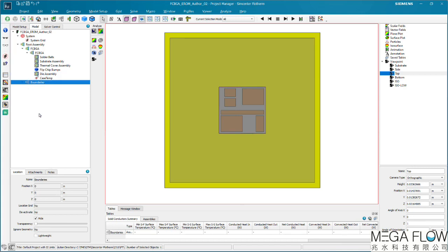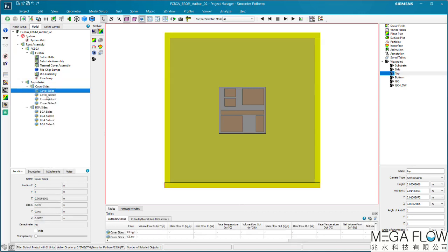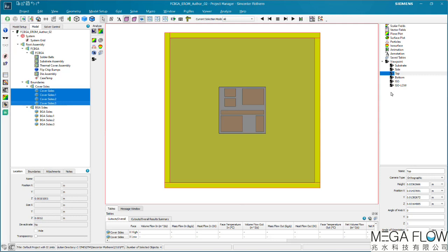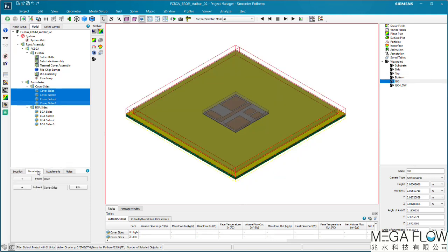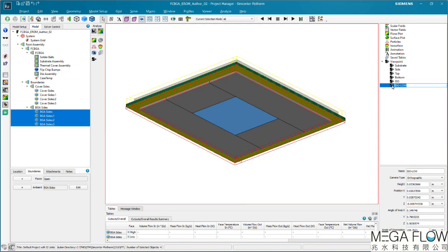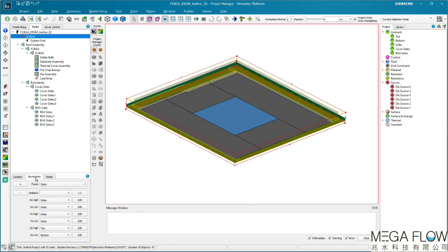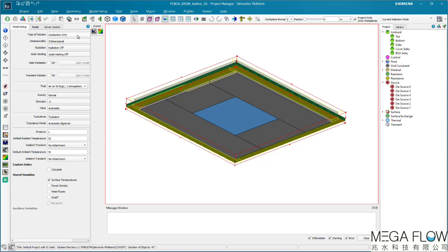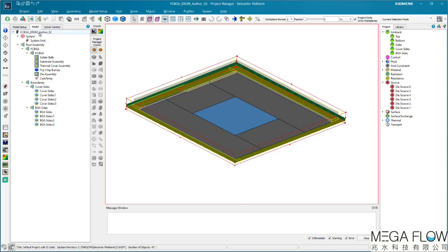The embeddable BCI ROM physical envelope is determined by the boundaries present within the model. To capture the footprint area of the cover and solder ball bounding volume, volume cutouts are used with ambient conditions attached. Ambient conditions are also attached to the solution domain faces with explicit labelling of the top and board surfaces. For embeddable BCI ROM export, the model is set to conduction only. To export the embeddable BCI ROM, the embeddable BCI ROM option is selected.